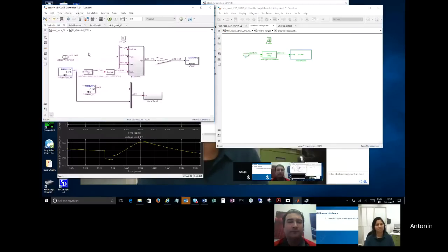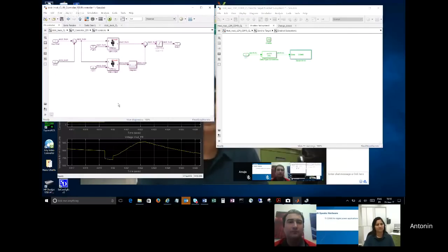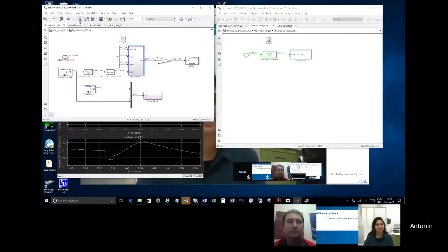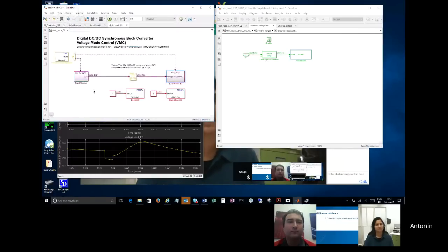If I look at this controller loop, it takes my demand, voltage demand, it gets the voltage measured, so the feedback from the ADC, and I feed that into a simple PI controller. Here is the P gain, and here is the I value with the integrator. I have a limiter here, so if the controller goes a little crazy, this will guarantee that the output is within acceptable boundaries. That pretty much covers what I have here.